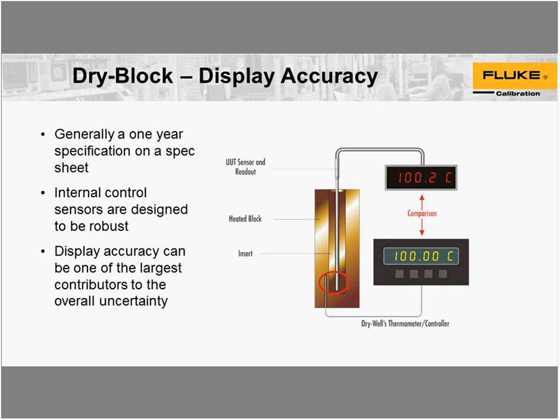Things to be aware of there, especially with a dry well. They are still typically an RTD type sensor, and they do not respond well to physical shock. So if you're shipping the units around or if they're a field unit, handling typically does come into play regarding the accuracy or drift of the sensor.